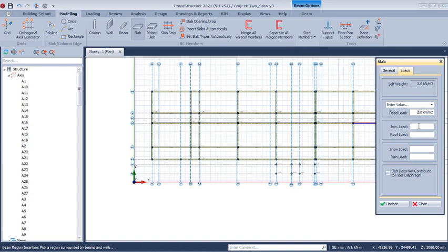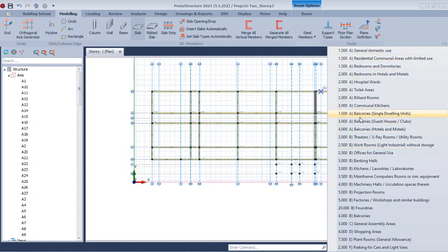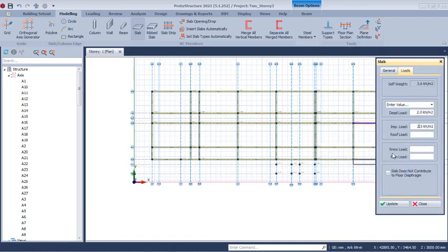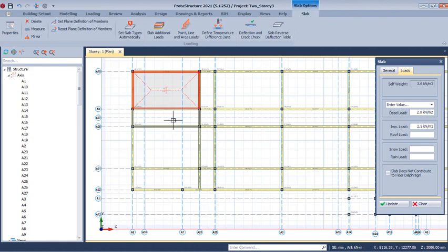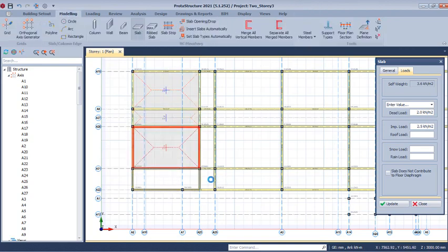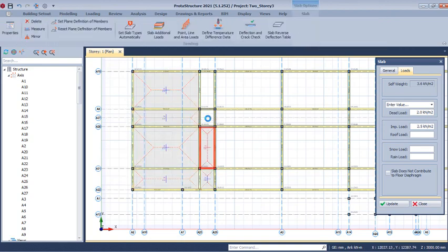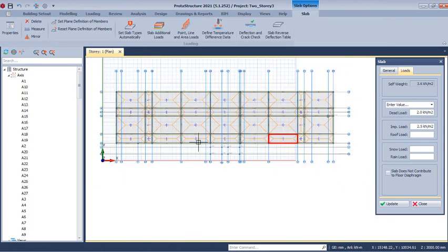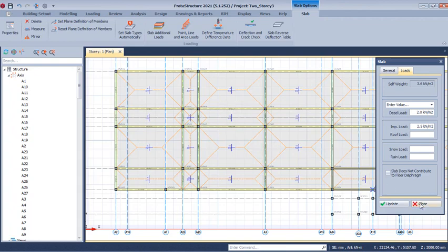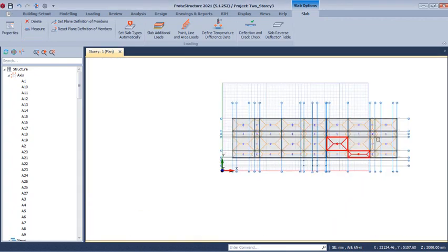For the live load, we'll be considering the live load for a commercial structure. So we can use 2 kilonewton per square meter. But I will want us to use 2.5. I'm looking for 2.5. This one I'll use 2.5 for schools. So at this point you just have to keep placing the reinforced concrete slabs just like this. After inserting your slab successfully, you just have to click on the close option here to have this dialog closed.